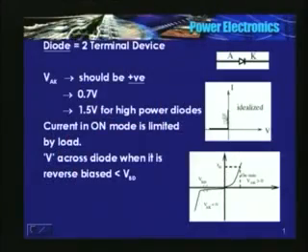When the diode is on, all of us know that the current in the circuit is limited by the load. The ideal characteristics are along the y-axis: it can carry any current, assuming it is less than the rated current, and it can block a negative voltage. It cannot block the positive voltage.